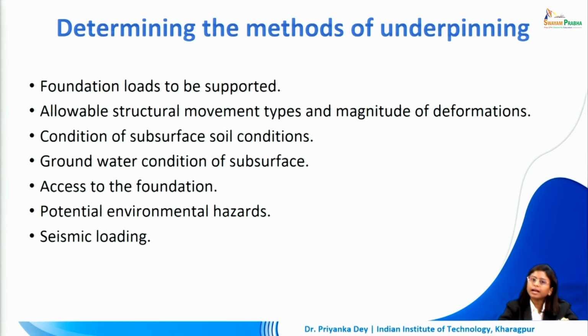We will definitely have to study the soil conditions in pretty much detail, knowing what is its bearing capacity, what are its challenges, its properties, its physical surroundings, vegetation, etc. that is impacting it, and every other aspect that might alter the health of this foundation. The groundwater condition also has to be studied, because if it is a very high groundwater table where just a little bit of digging exposes water, we cannot use any and every type of underpinning, as it will become clearer when we study the methods.